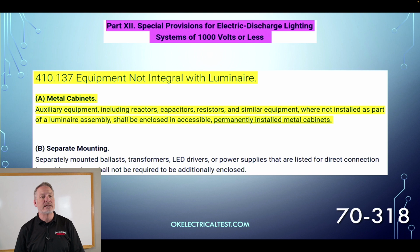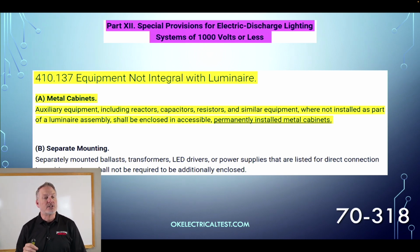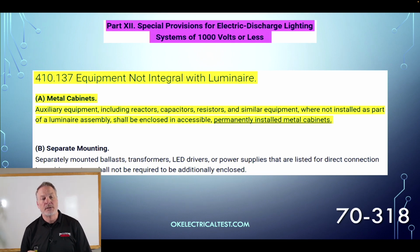Let's move to 410.137, and you'll notice we'll transition into Part 12, which is special provisions for electric discharge lighting systems of 1,000 volts or less. 410.137 is equipment not integral with the luminaire. It says in letter A, metal cabinets. Auxiliary equipment, including reactors, capacitors, resistors, and similar equipment, where not installed as part of luminaire assembly, shall be enclosed in accessible, permanently installed metal cabinets. So it needs to be accessible and permanently installed in a metal cabinet.